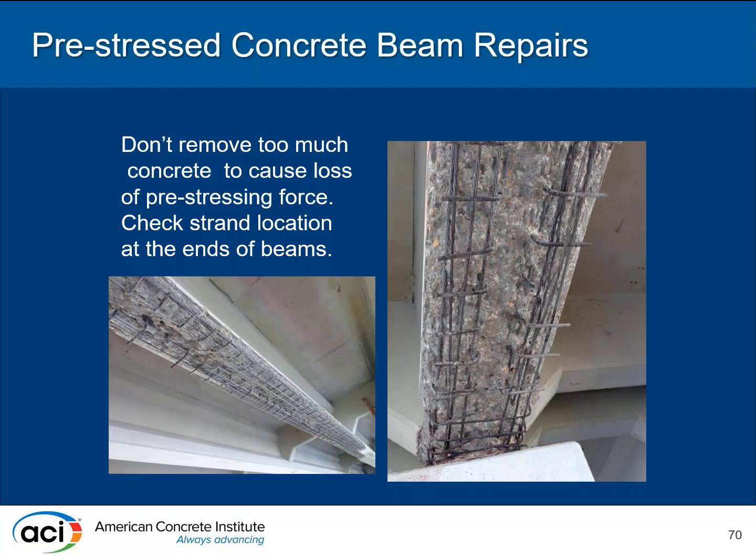You could lose your anchorage, or you could cause the beam to deflect excessively, or crack, or fail. These types of information, the person who is most familiar with the structure is the licensed design professional, and needs to provide guidance to the contractor on what they can and cannot do. This isn't determining their means and methods. It's not saying how they remove it or how they do that, but just providing a limit so that they understand what they have to do in the box that they're playing in, kind of thing.